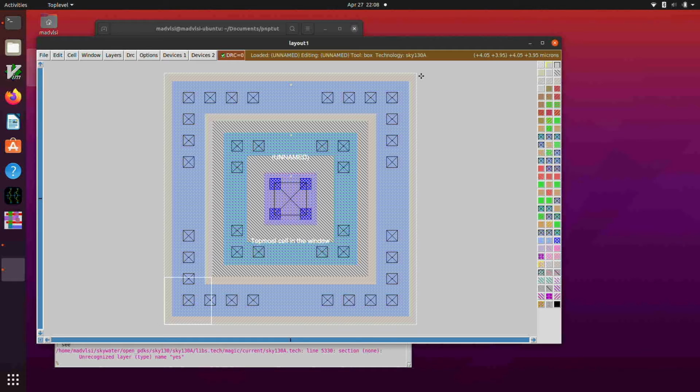So they probably sent this device out for fabrication. They characterized it. They tuned their model parameters to match the characteristics of this device that they fabricated, and this is what you can use. So it is possible to draw a device like this with layers that are here, and it will extract just like this device will, but it is definitely an off-label use for the technology, and the models are not, if you like, warranted by the foundry to match those devices.